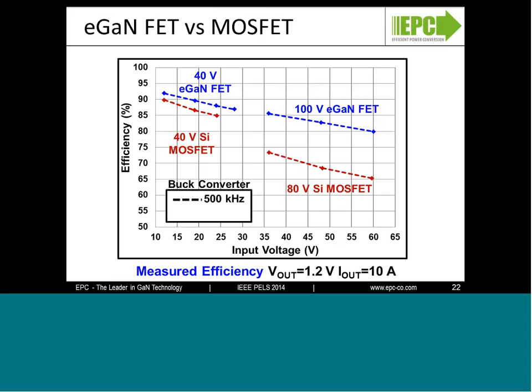the eGaN-FET increase. And then when you switch to the higher voltage cases, we ran at 36 volts, 48 volts, and 60 volts. You need a higher voltage device. And as you go higher in voltage in device, you also have a general increase in switching charge.